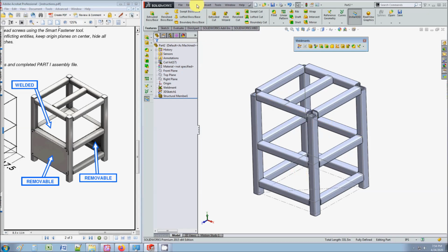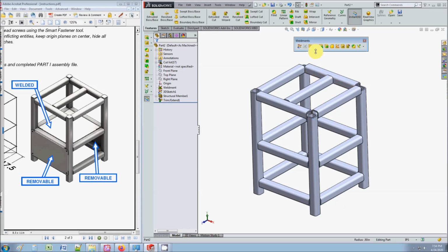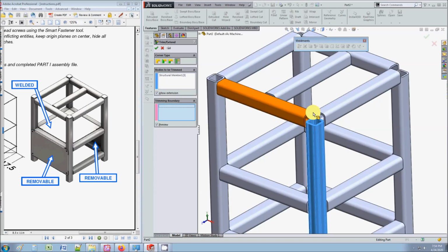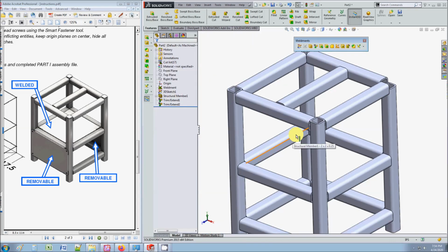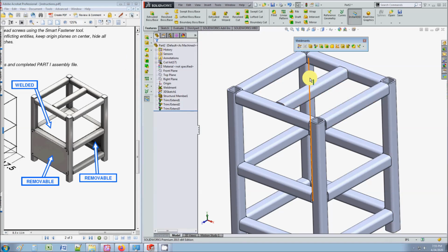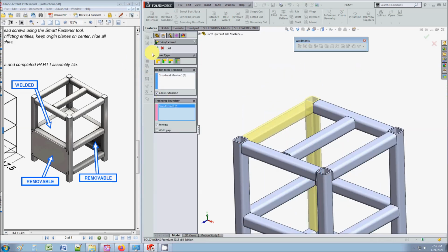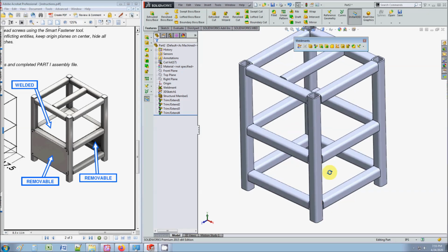So we don't really need the construction lines anymore, so I'm just going to hide all types. And I'm going to trim and extend. As you can see, this goes out to here. Just going to switch this. There we are. Okay, one there. If you hit enter, you may be able to repeat last command if it's configured like that. If not, it could be Y, if you hit the Y key. For me, it's the enter. Otherwise, just keep clicking that button. Okay, there it is. Enter this one up to here. Okay, 1, 2, 3, 4. All right, those look good.